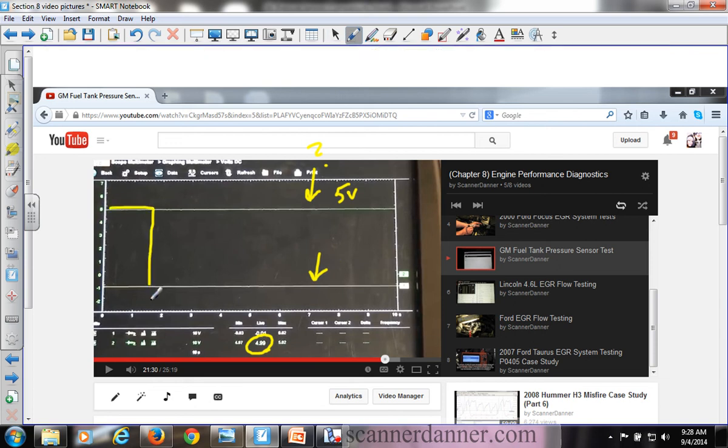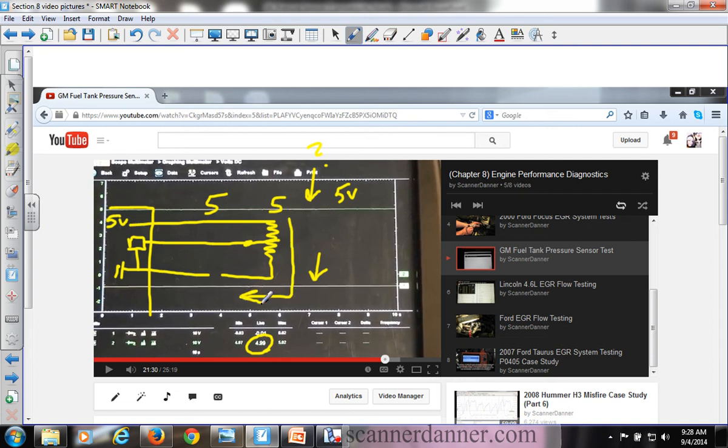If I have a sensor, it's 5 volts across the resistor, and we'll make the ground be open. Signal circuits here. This is going to be 5 up here, agreed? Five volts here, and without current flow, no voltage drop, so this is 5, 5, 5. What's the signal voltage going to read? 5 with a bad ground. I'm not worried about the ground, based on my voltage signal.